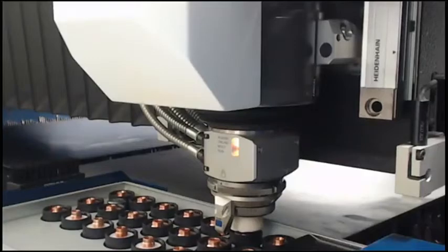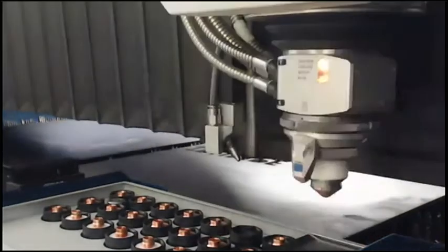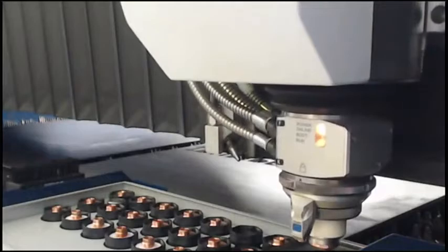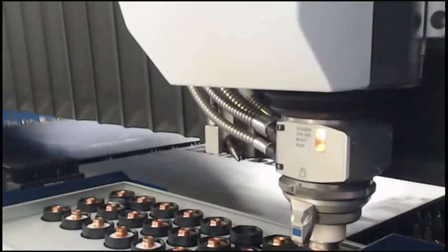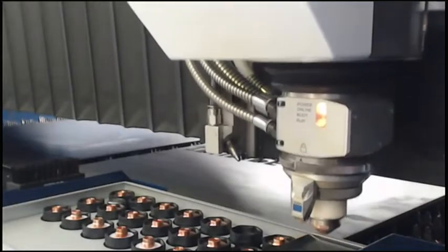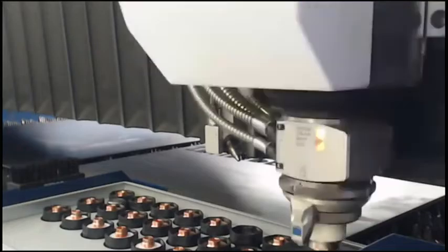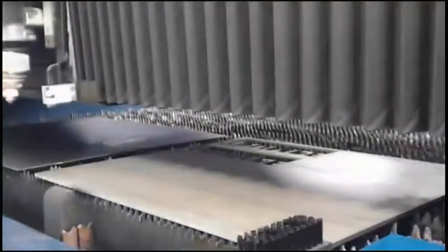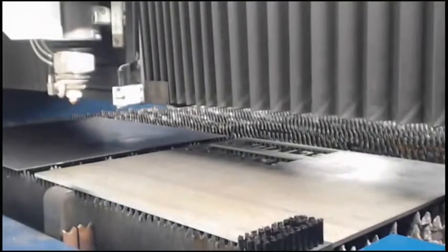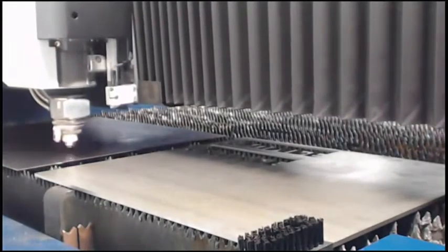So cool, the thing we're going to talk about is the nozzle change. Y'all will notice that we're not worried about alignment or anything. You'll also notice we're screwing the nozzle in. When you screw the nozzle in as opposed to pushing it in, you don't have to worry about the alignment of the beam to the center of the nozzle. So it allows us to go quickly and reliably from nozzle to nozzle.